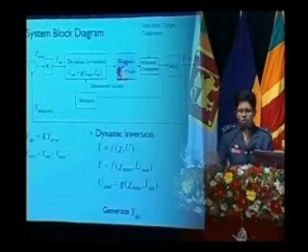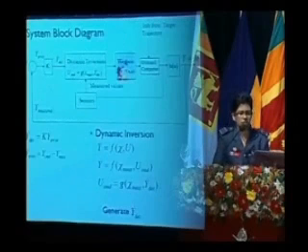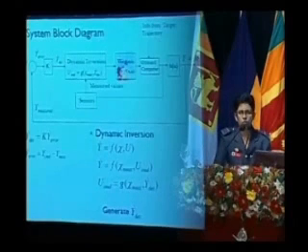This is the system block diagram, where you can see the dynamic inversion is applied to the closed loop system, and information of the trajectory is sensed by some remote sensors and fed into the system. So in the end, what it is doing is getting some measured values, it has a command input, and it is generating the error signal, and with time we are trying to drive this error signal to 0 to get the desired output.